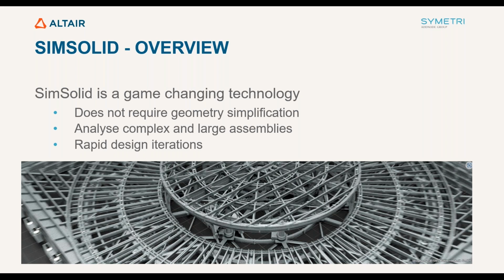The main emphasis is that it doesn't require any geometry simplification. In the FEA market you normally have to do simplification and create elements, and in the structural world you have to specify beam elements. It doesn't require any of that work and effort, which means you can spend more time on the analysis. It can work on very complex geometries and very large assemblies. The other benefit of SimSolid is that it doesn't require a supercomputer. It operates very, very fast, and you'll see that when we go through some of the examples.